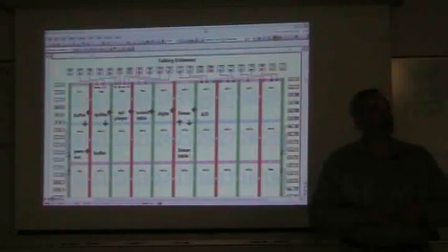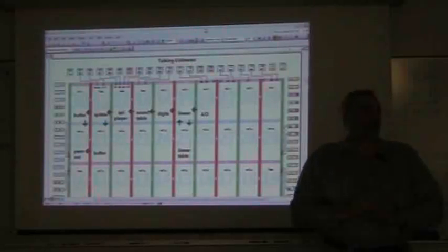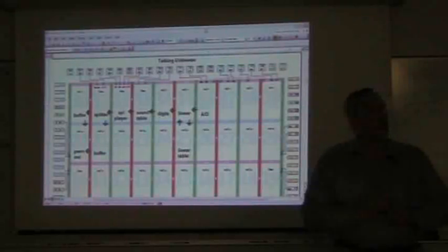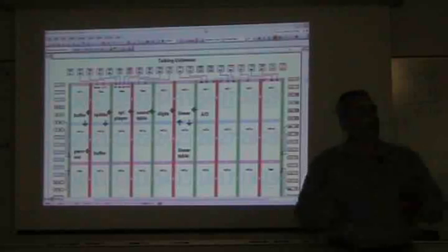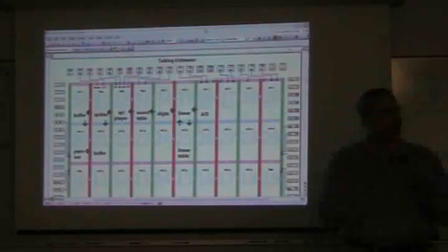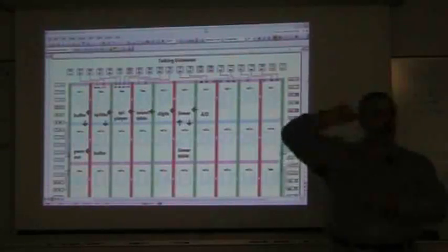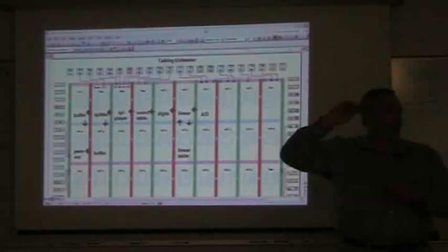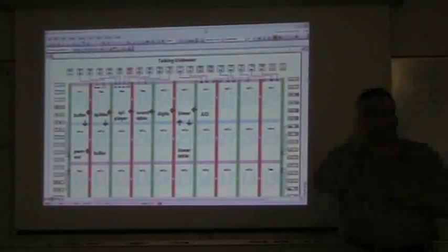And I did a couple other little tricks using the table that way. For instance, I cleaned up the sync and blank signals because our sampler samples over a window, and because that window is variable, and because we had it set for a pixel length, it was possible for you to sample while going from blank through a black pixel, and you'd get these positions that were not clearly defined as either sync or blank, but sort of halfway in between them.